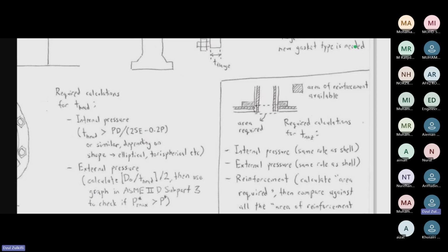When you cut a hole in the shell, you have to make sure the metal that used to sit in that hole is compensated with neighboring material. That's why many nozzles have a reinforcement pad at the edge of the nozzle. So the edge of the nozzle is thicker so that it can have that compensation, so that it becomes reinforced. If you have a hole in the middle of the shell, that hole becomes a weak point, a stress concentration, and you need more reinforcement on it. There is a certain formula to find out that reinforcement.